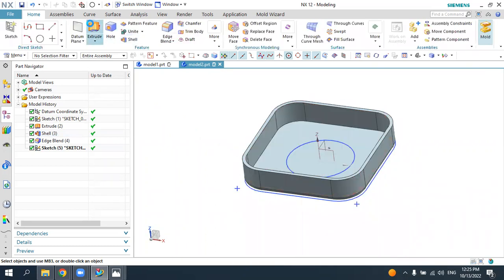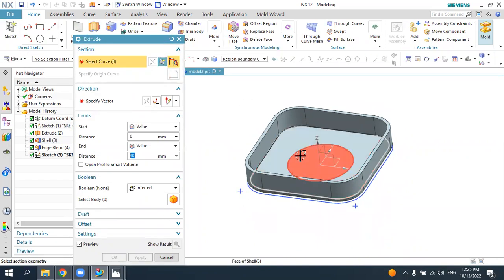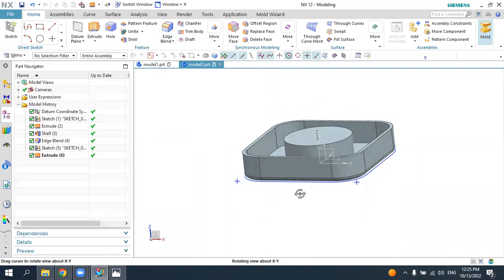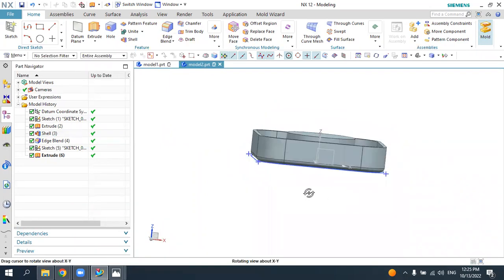So now we will extrude it at the distance. Here you can make it a single. It does not matter. So just a single element. So we will extrude it at a 30 millimeter again here, and just press OK. So we created our element here.